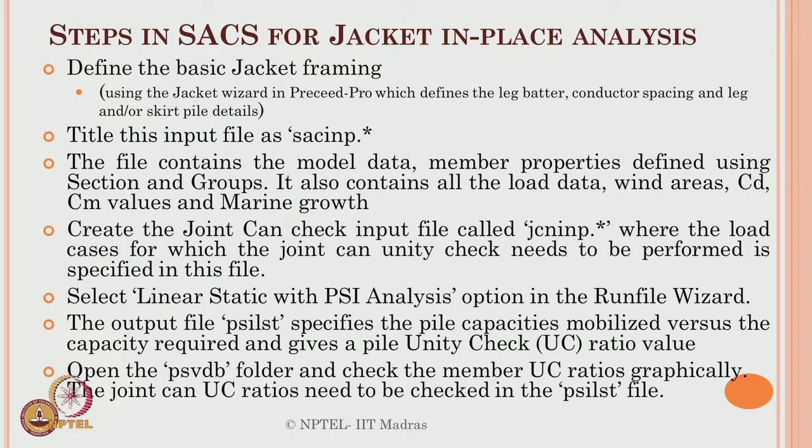Let us quickly see what are those steps in jacket modeling in SACS in general for in-place analysis. Define the basic jacket framing, use the jacket wizard in Precede Pro in the SACS module, which defines the leg batter, the conductor spacing, and the leg and skirt pile details. Title this file as an input, SACINP star dot star.